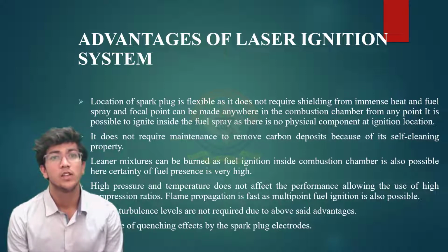Here are the advantages of the laser ignition system. First one, the location of the spark plug is flexible as it does not require shielding from immense heat, and fuel spray and focal point can be made anywhere in the combustion chamber. From any point it is possible to ignite inside the fuel spray as there is no physical component at the ignition location. It does not require maintenance to remove carbon deposits because of its self-cleaning property.